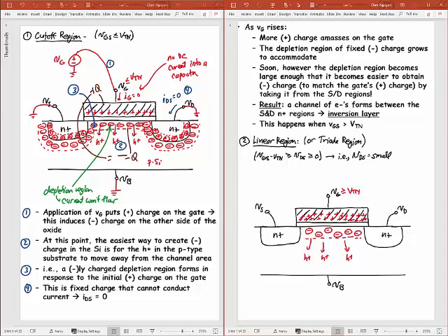And so what it does instead is start stealing charge from the N plus junctions out here. Okay? And so suddenly, instead of more of this static charge forming, I now form what's called a channel. So that red now is a channel of electrons. Mobile carriers here. And what that's called in MOS language